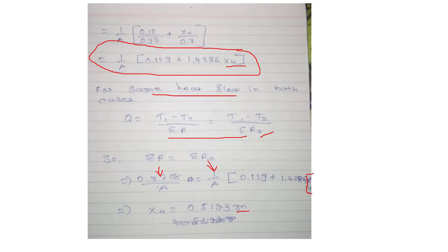Mind well, in the heat transfer subject, in the numerical, thermal conductivity or any other terms are mostly given in meter unit. So we will use the thickness of any material in meter.